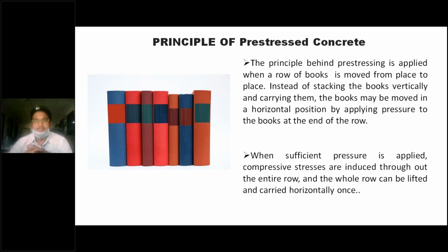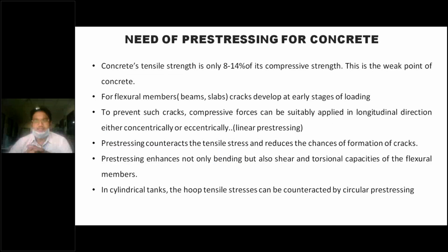Okay, I hope you all understand why this pre-stressing technology or pre-stressing concept comes into the picture, in terms of understanding RCC and PSC better, right? Next, what is the need of pre-stressing for concrete? Can concrete alone, based on its compression strength, not carry the working loads? No. So there is a need for pre-stressing concrete.